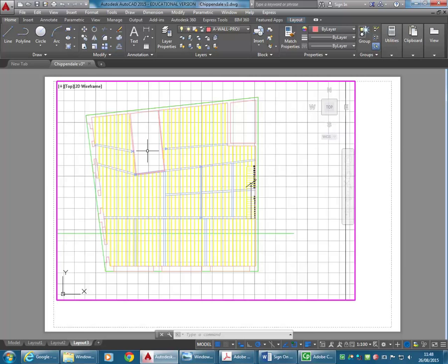And that's exactly how we'll get the electrical drawing, because in the electrical drawing, it's going to help to have the joists done. That's why we had to do the joists first, because those light fittings sit on the joists. So that'll help you to position the light fittings. But you probably don't want to see the joists in that electrical drawing. It's just going to make it too confusing. So we can also freeze that layer in your electrical drawing. But the reflected ceiling plan, in its raw state, will show the joists, so I'm going to leave them on here.